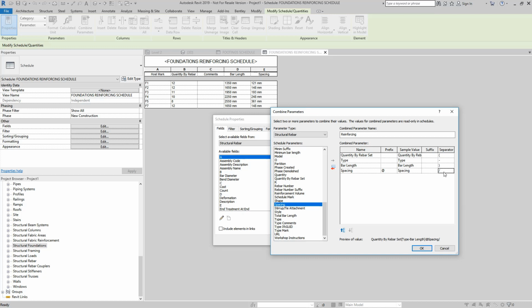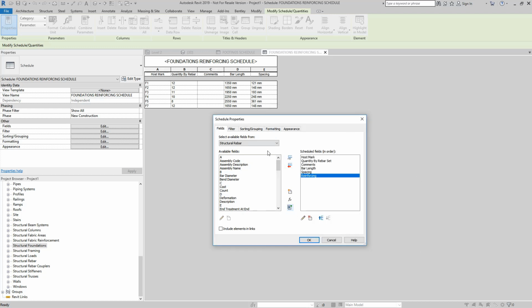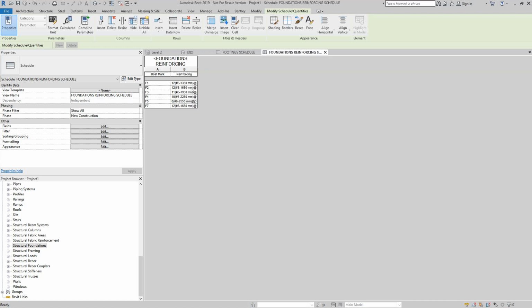So here we have the number of bars, X number of certain size bars for a certain length at spacing center to center, bottom face each way. Remember, because of our reinforcing design, we're forcing it to be a square, and because of some design options we checked in RAM Foundations, we can afford to do this. So the number of bars in both directions are the same, for the bottom face at least. So this is the schedule we have, okay?